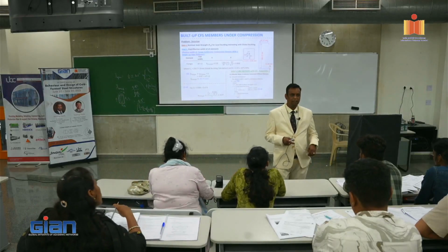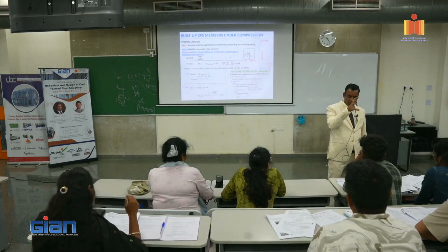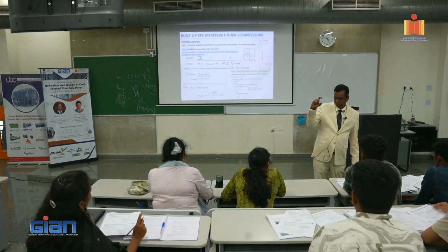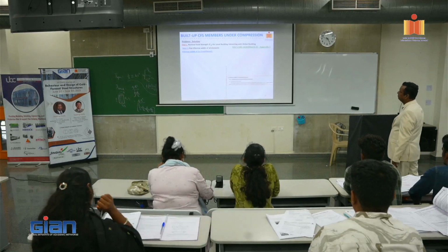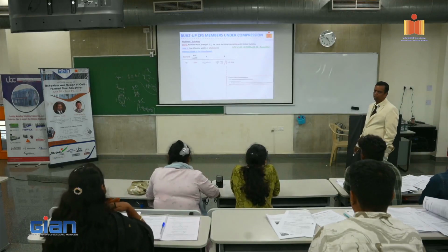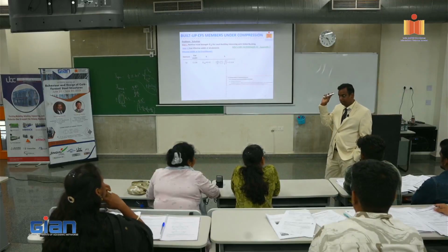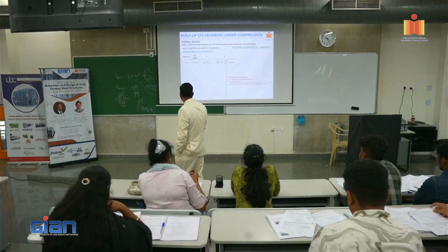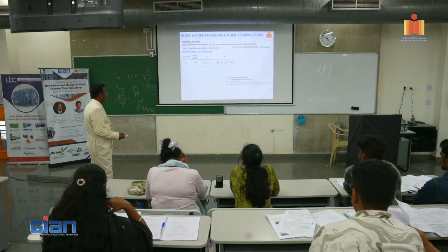There are 3 things, right? We have the web fully stiffened, flanges partially stiffened, unstiffened is lip, right? So we have to now go to the unstiffened portion, which is effective width of the lip. If you look at the lip, the flat width is 11.04, right? Don't get confused with the total depth, which is 15 something. That is only for calculating W by D. No? Okay, so this flat width is here, lip, 0.43, right? So when you do so, you get 0.324, right? 0.324 is what? Less than 0.673.